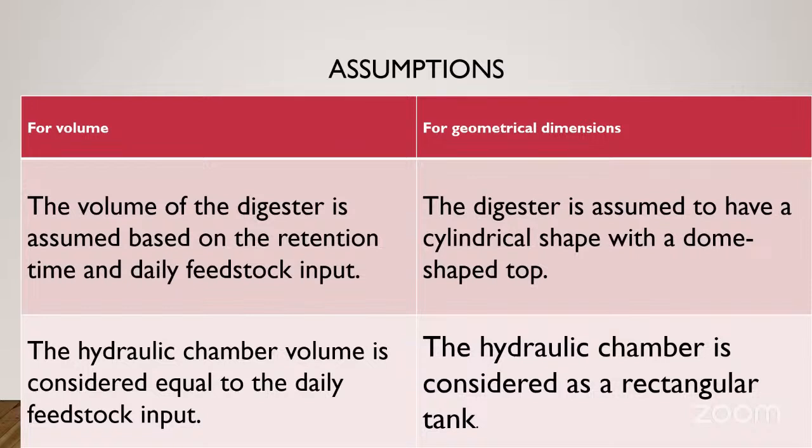So when you are computing the gas which will come out of your digester, you can make a number of assumptions. Among those assumptions, you can say the volume of the digester is assumed based on the retention time and daily feedstock input.